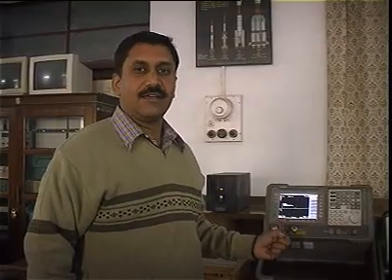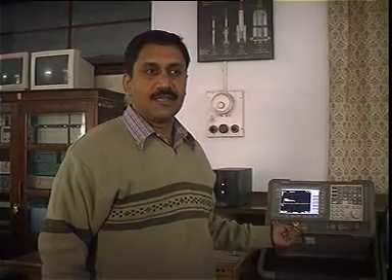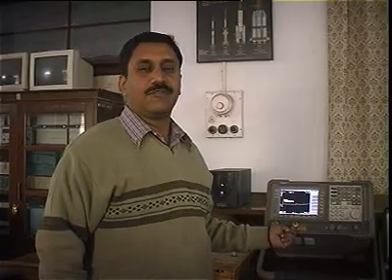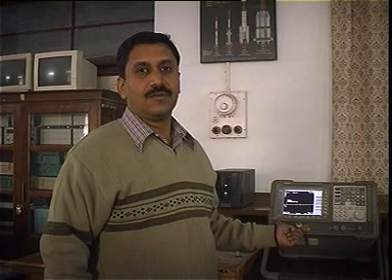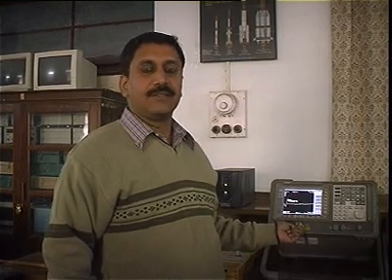So that is why I cannot connect an arbitrary cable to this input. I must connect a cable having a 50 ohm impedance to this input. Likewise, if you have a video signal, you will have a 75 ohm input impedance cable. So you will have to connect only that kind of cable to this input. Okay? I cannot arbitrarily connect any kind of cable to this input. You can still display the signal, but the power content that is displayed on the screen will not be the same as that which is being carried by the signal. Okay, so that is very important.